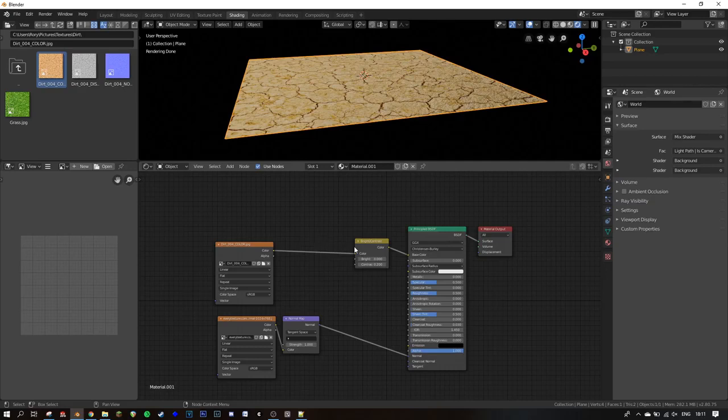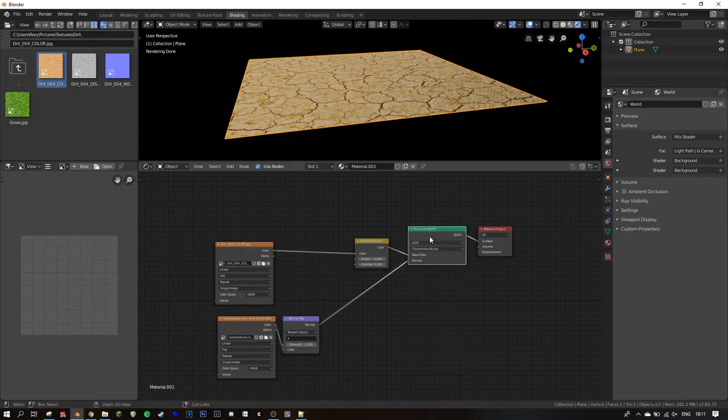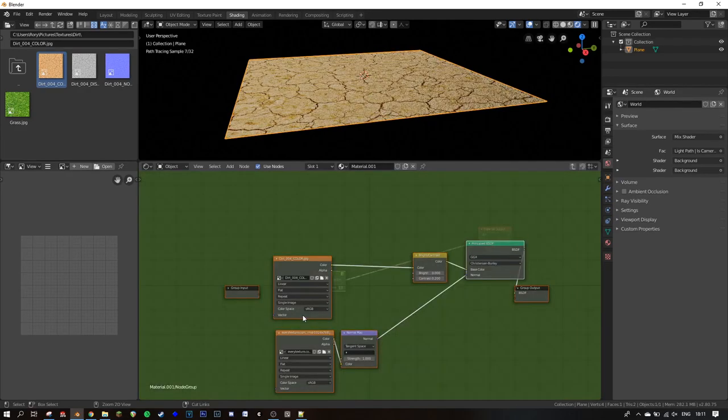Now we've finished editing the principled shader, we can click it and then do Ctrl H to hide the unused nodes. Now we can create a group out of the whole left section by left click and dragging to select them all and pressing Ctrl G. If we want to control any of the parameters, say the normal map strength, from outside the group, we can drag its input to the group input node.